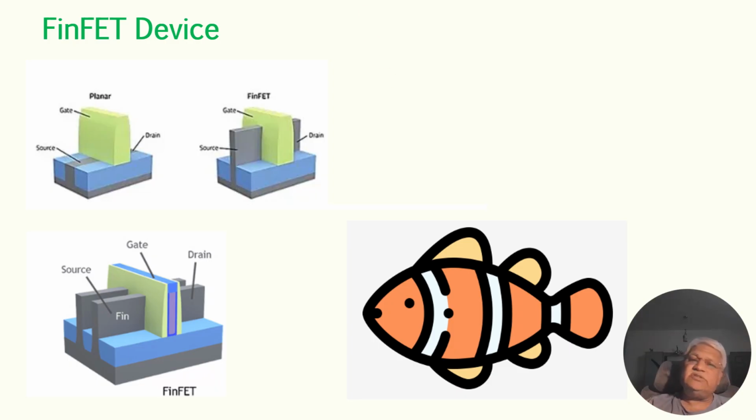As you know, wafer cost of 5 nanometer is way higher than of a 28 nanometer or 22 nanometer wafer. Why? To know about that, we need to know one important point. That is, the transistor channel length is not the only feature that must be patterned. There are other dimensions in the FinFET, which need to be taken care of in a very specific manner and in a controllable manner.